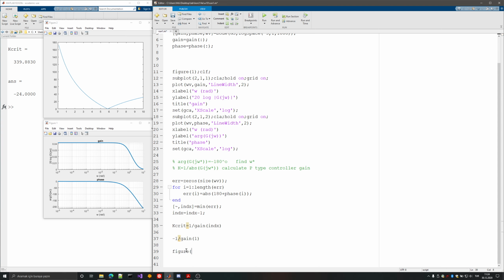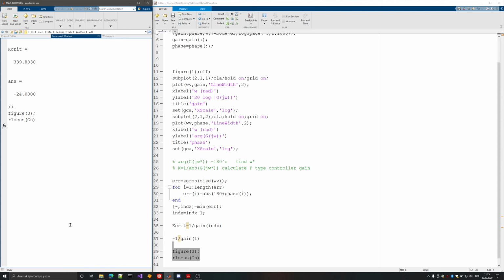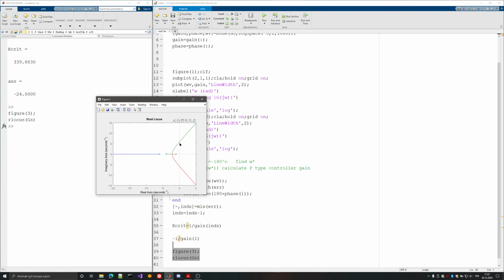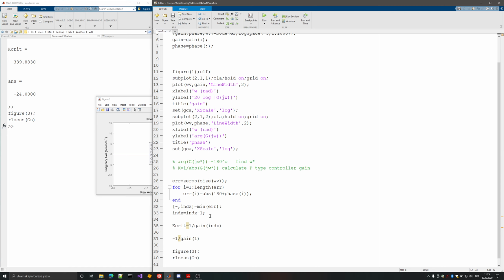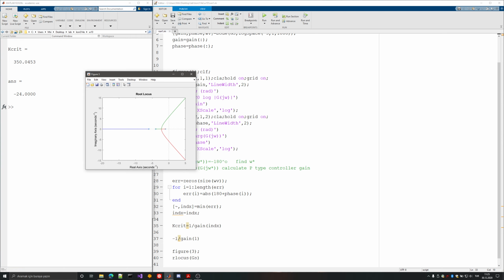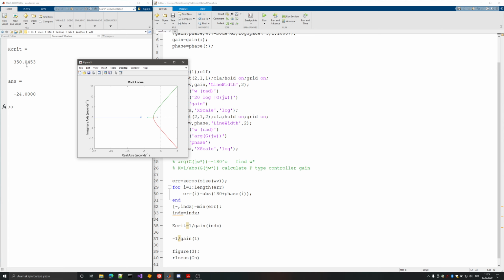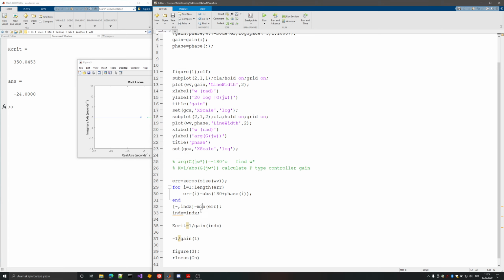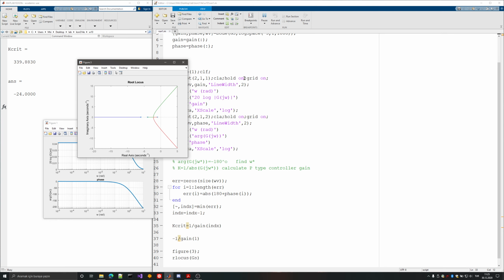So let's look for this information using the time domain. So in this root locus, I have to click somewhere around here because this is the j omega axis crossing here. Hopefully. And you can see that the 344, since I've used -1 and a bit more conservative in order to end up with a stable bound, you can go ahead and calculate this 344 if you're not that conservative. Let's basically try this point here. It is 350, and you get what I mean. Because Bode plot is not that much detailed, you might miss the exact point and you might end up somewhere here. So being a little bit conservative makes sense in that case. Or you have to increase your grid, but still it is important to be conservative.